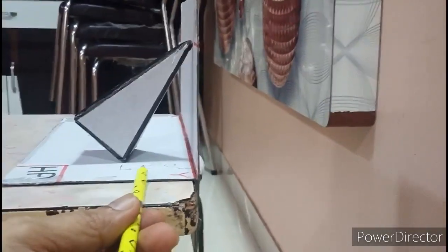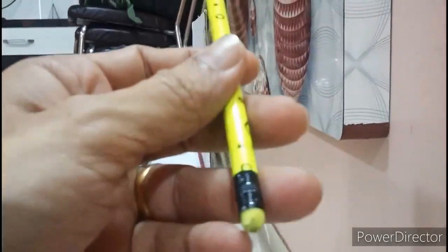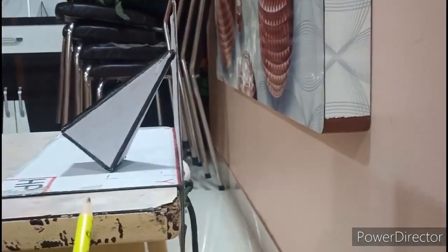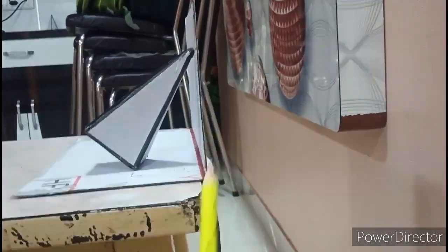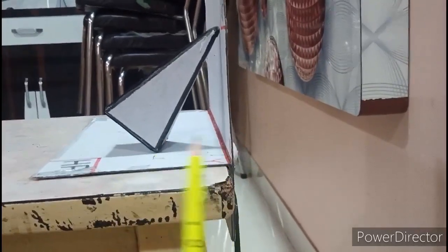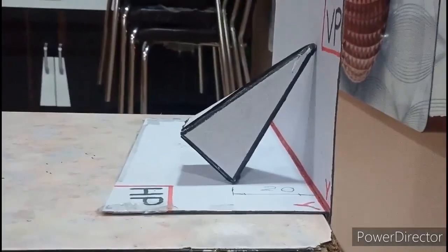So now how to break this into 3 stages, let us see. So let us go in the side view and focus on this 20 millimeter. So if you look thoroughly, this is 20, right? Okay, so in side view, this 20 millimeter is the horizontal distance. This 20 millimeter is nothing but the horizontal distance between the resting edge AB and the apex. So if you draw a vertical line from AB, and from apex if you draw a vertical line, that horizontal distance is 20. Okay, so this is the third stage, front to top view.